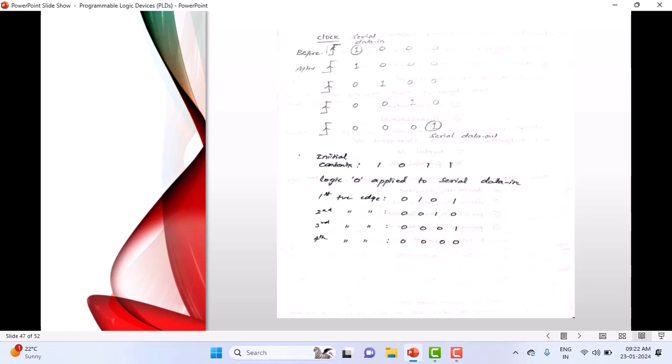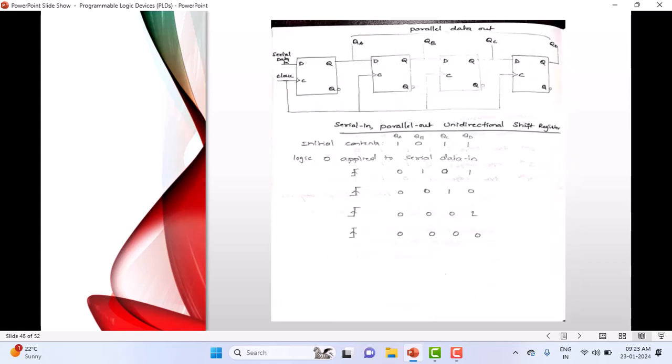This is one way you can see that. I showed rising edge here in the above. This is another example I showed with rising edges. When the rising edge comes, how does data change? Here I have inputted logic 1. You can see that the 1 has been moved serially to the outside. This is how the shift register works. And I think I have shown one more example.